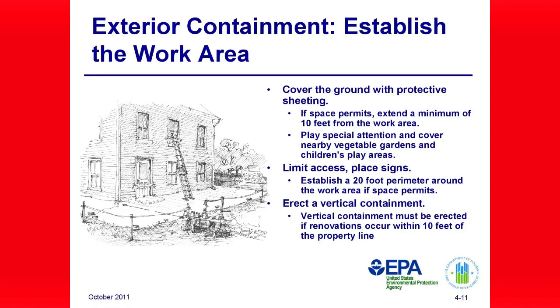Erect a vertical containment. It's required if the property line is within 10 feet of the work area. If it is not, then you can just do the plastic and then do the notification or limit the work access immediately thereafter.